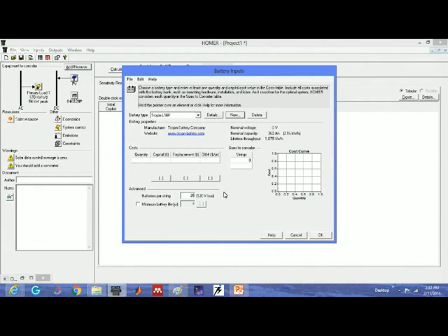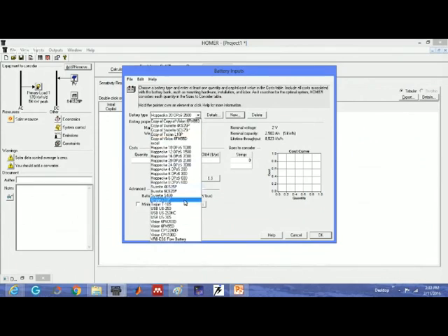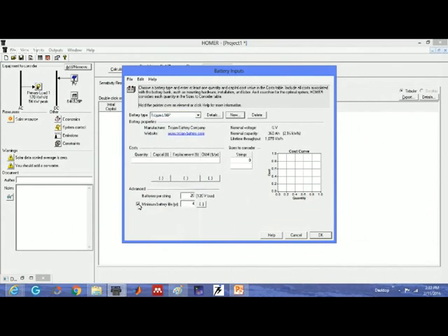So if I choose a different battery, let's say this one. This is a 2-volt battery, but ampere hour is very high. See, 2500 ampere hour is there. So I will take again now 20 batteries. The bus voltage is only 40. Right. So if I want to make a bus voltage of 120, I need 60 batteries. So it's up to me how much I am going to use. See, I'm just taking it. Now minimum battery life, again, that is a sensitive factor. What is the minimum battery life?